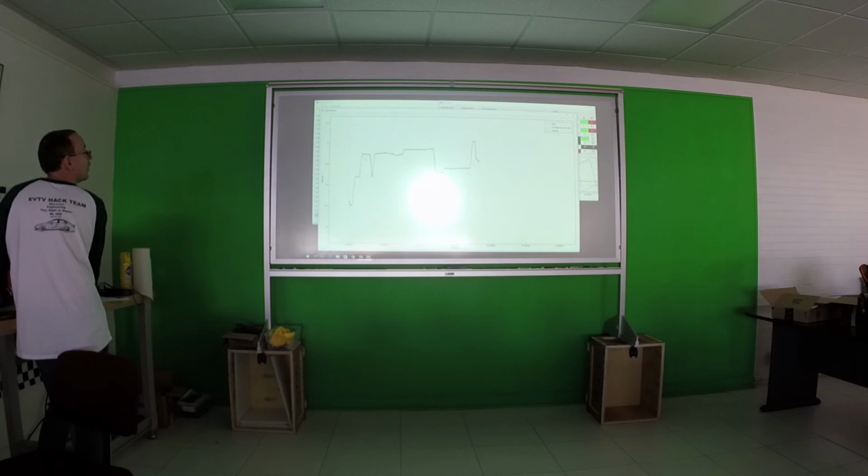I've scaled everything over top of each other. What we were doing here is trying to see, quite often the Tesla has quite a bit of data that is duplicated on the bus. Here we have 3 signals that I've pretty much worked right over top of each other. Or no, those 2 signals are almost over top of each other. This, I think, was miles per hour. And these are throttles and some mystery signal that we didn't know about.